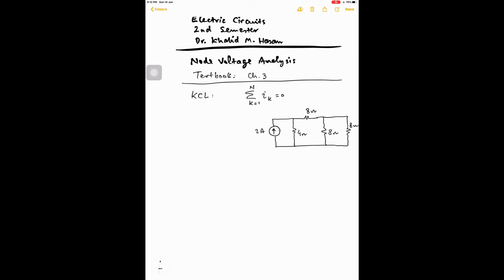In this circuit, we have a node here, another node here, and the bottom node over here. We can put a dot over here, but this is not an additional node. So first of all, we identify all the nodes and we select a node as a ground node. So here we can select this node as a ground node. So at the bottom we have just one node. Putting a dot doesn't mean that it is necessarily a node.